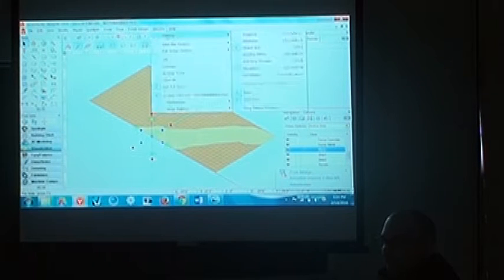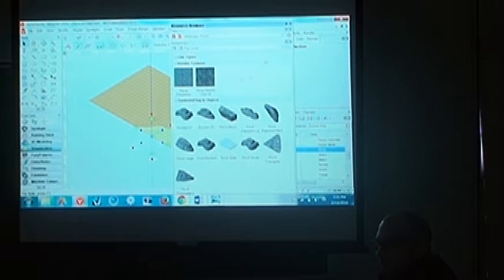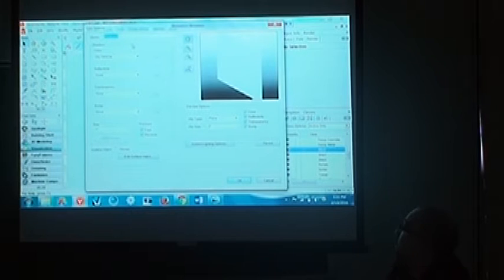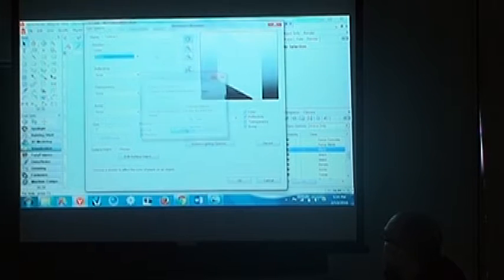I don't have my resource browser open right now, so I'm going to open it. And what I would do is say I want a new resource and I want to create a RenderWorks texture. So this is the box for creating a new texture. There are 4 shaders that contribute to a texture. Color: under color, I'm going to say I want the color of this texture to come from an image, and then I can import an image file. Why don't we go ahead and import.